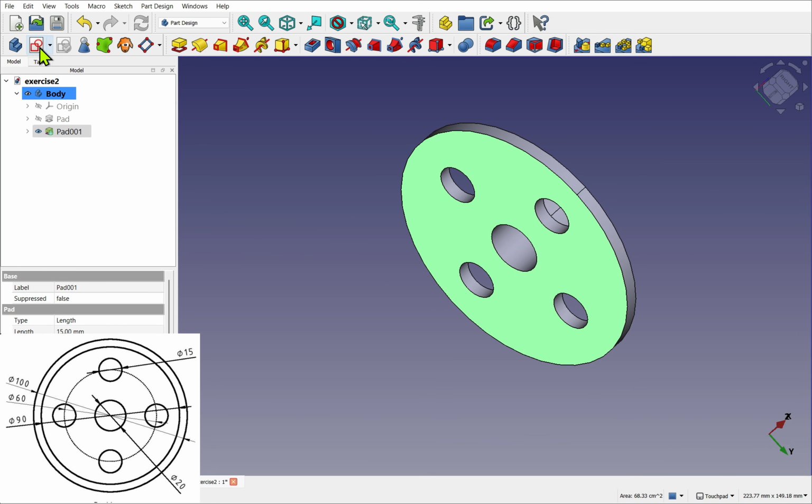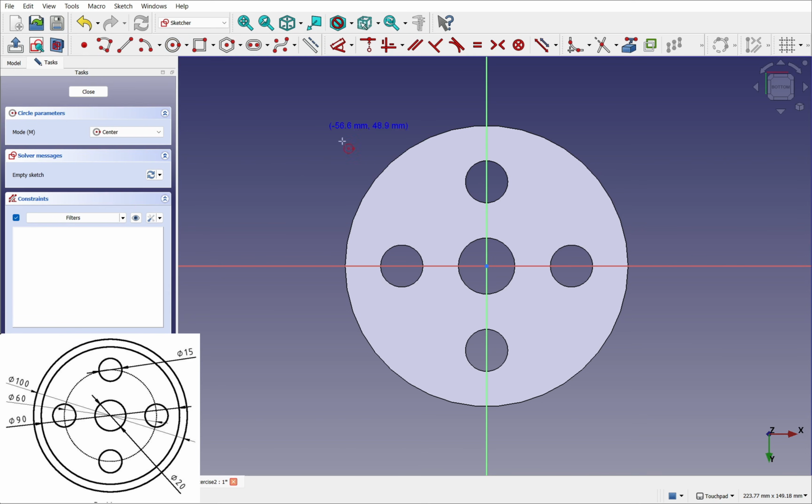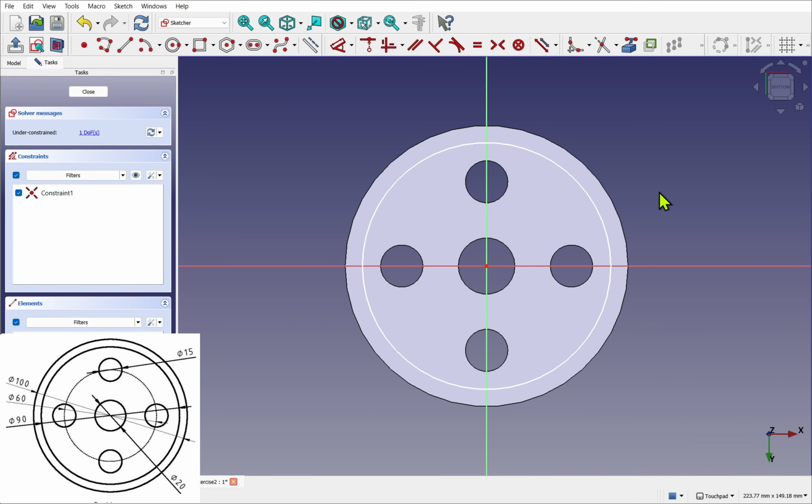And now I can create another sketch which can be applied to the bottom. We'll use a subtractive feature to remove volume. And it's exactly the same for creating sketches for additive volume. So we just click on the circle, hover over the center point, and bring this circle out. Dropping it, right clicking, and then using the dimensioning tool.